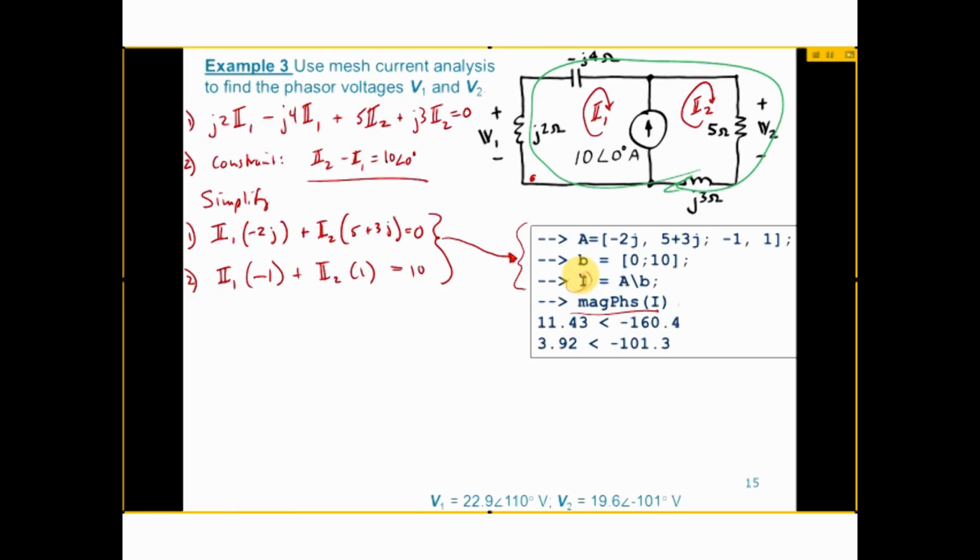And then the last step is to take those currents and solve for the phasors V1 and V2. So phasor V1 is going to equal what? Okay, but how do I get there? How do I derive V1 from my solution for I1 and I2? If I know what I1 is, now I have to write an expression for V1. It's just Ohm's law, right? So I1 is flowing this way. V1, the polarity though is this way, so Ohm's law says V1 is what? Yeah, keep going, please.